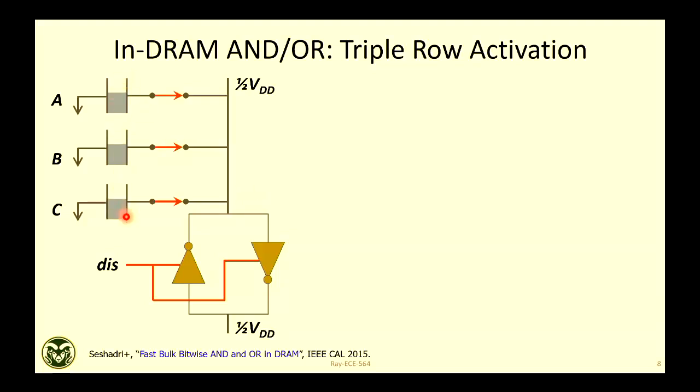There will be charge sharing taking place, right? This full capacitor will discharge, and all this capacitor will come to the same voltage, because this is the whole point, right? Charge sharing means after charge sharing, all the capacitors will come to the same voltage, because they're in parallel. Okay, and then you'll get a delta plus delta here, because you start with 2 cells being fully charged.